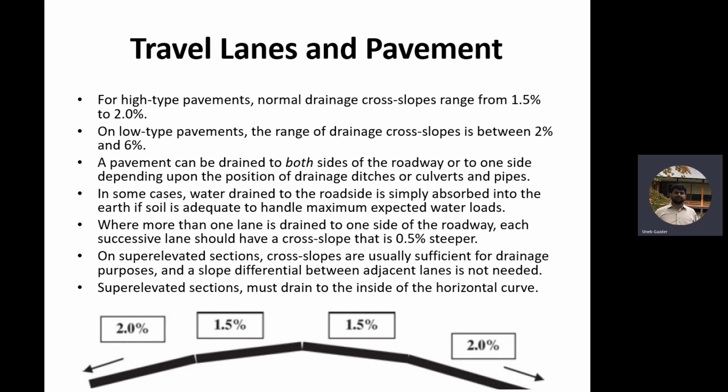Can we have this cross section on the curves? Like this, can we have both side drainage on the curve? No. Because superelevation is only, you have to raise the outside edge. There's nothing like this.